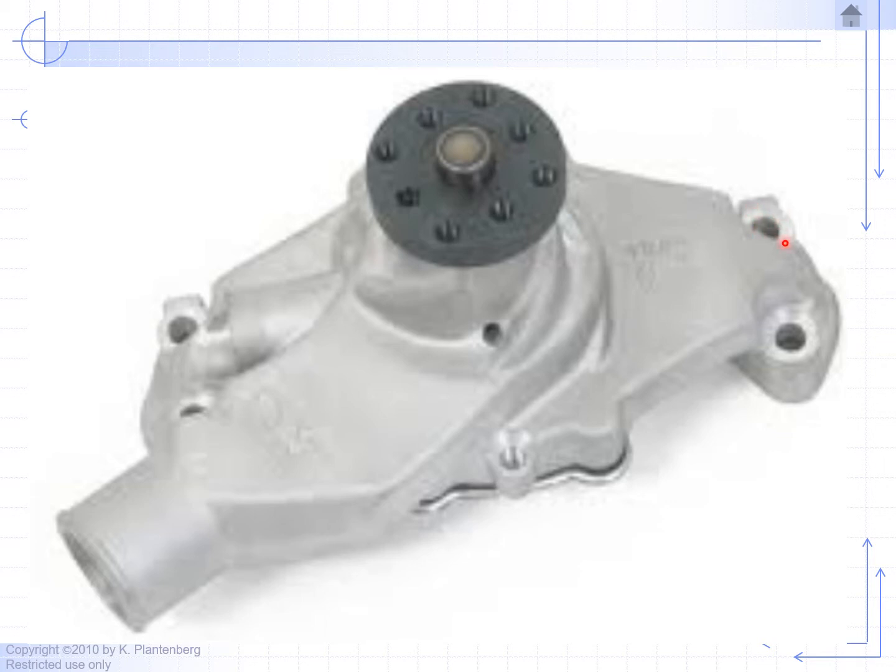So you're going to come in and machine these surfaces. These are referred to as spot faces. So before they were machined, you had a contoured surface here. So you come in and you drill your first hole, then you come in with your second hole, counterbore hole, and you come in and drill, and it's going to remove some of that rough surface with contours. So you're guaranteed to have this surface parallel to the base. Same thing with the other four. You have the top surface of the counterbore hole parallel to the base.